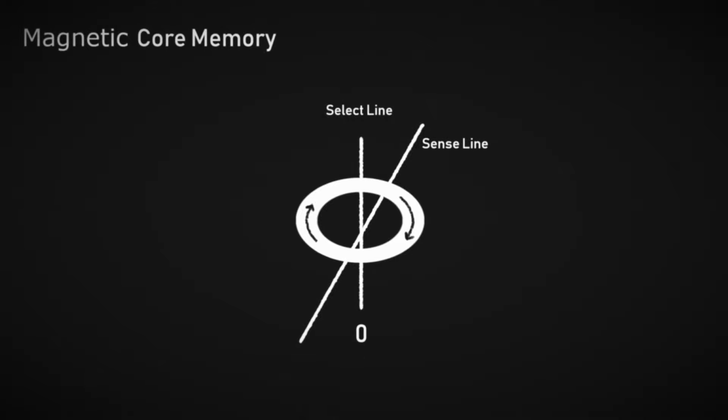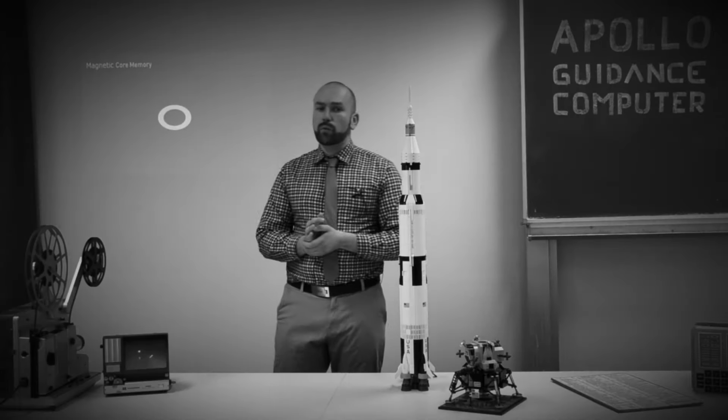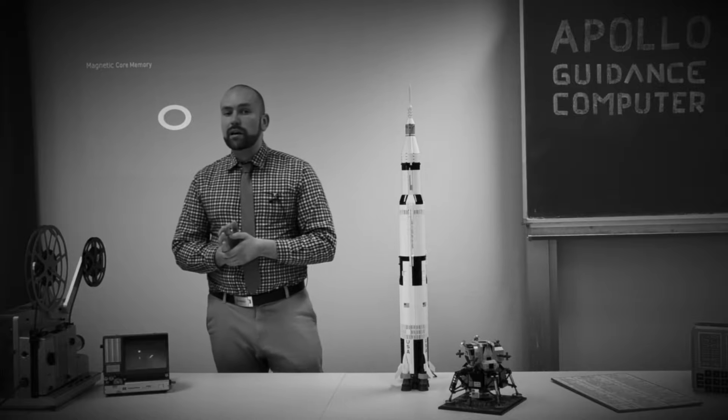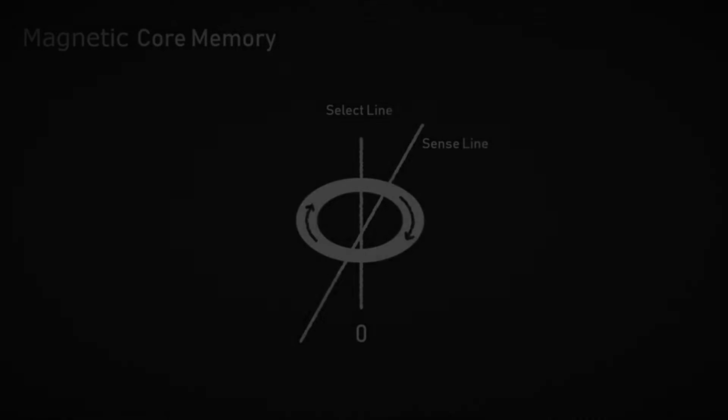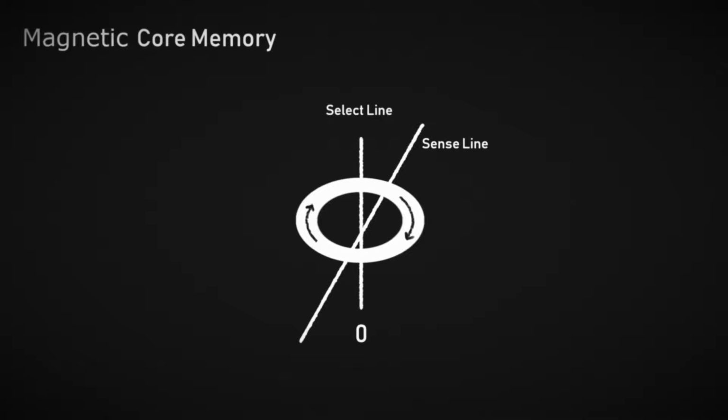When the core originally holds a 0, again we write a 0 to the core. But because the core already stores a 0, there is no pulse on the sense line, which is interpreted accordingly. In the next step, we would again apply a reverse current, as we did when we read out the binary 1. In order to prevent that, we write a 1 to the core supposed to hold a binary 0.